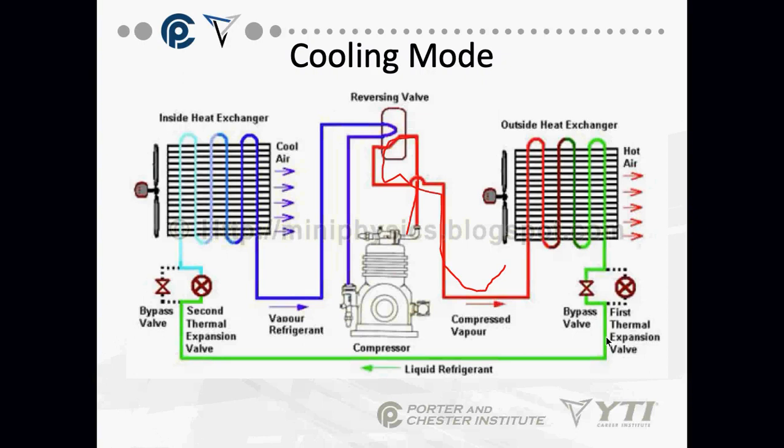Yeah, I mean, the bulb that tells the TXV how much. Oh, the bulb. Okay, yeah. The bulb that's attached to it, yes, goes on the suction side. Always. Both of them. Yes. Well, but it depends on the suction side for the mode it's in. Okay, so this TXV, the suction bulb would be mounted there. Okay, because it's not being used in the cooling mode.